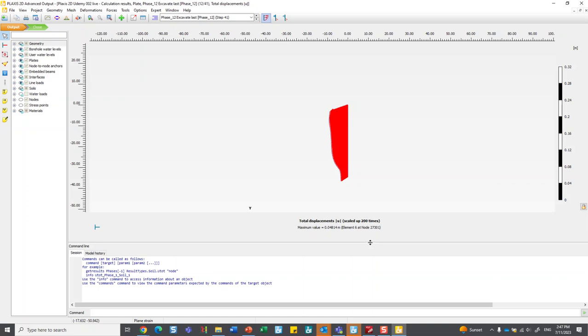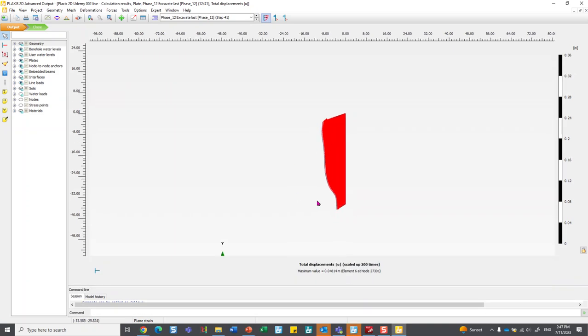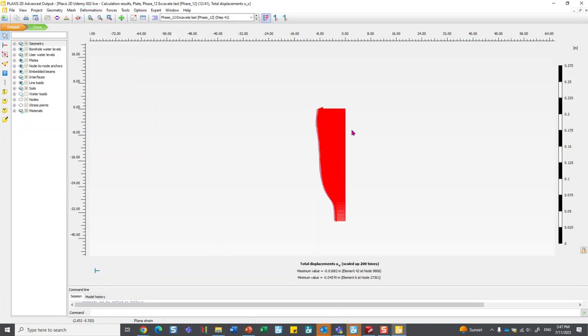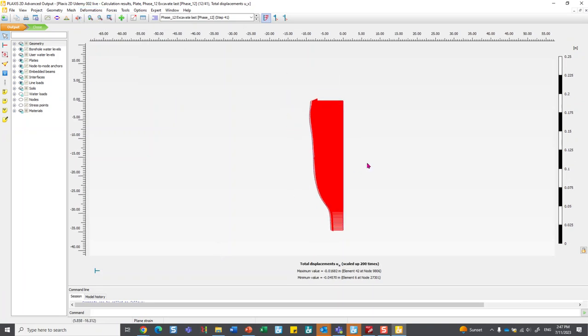It's telling you that this plate will deform a maximum value of about 48. That's U. This is a total deformation, which is counted from the moment we zeroed the deformation, if you remember. If I'm interested in the lateral deformation, I can say give me UX. This is a distribution where I have a maximum value here of 45, 46 millimeter going into the excavation.